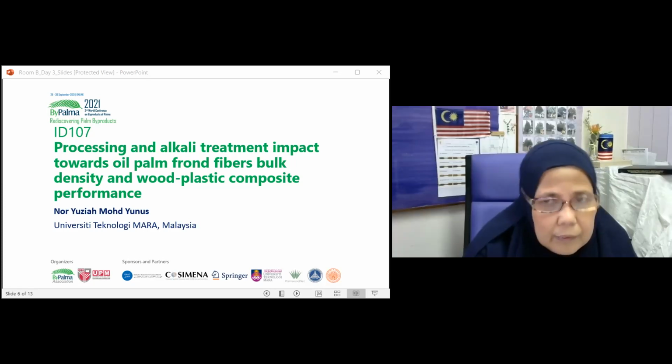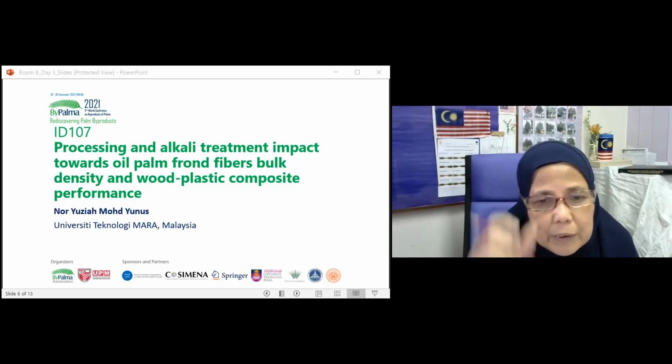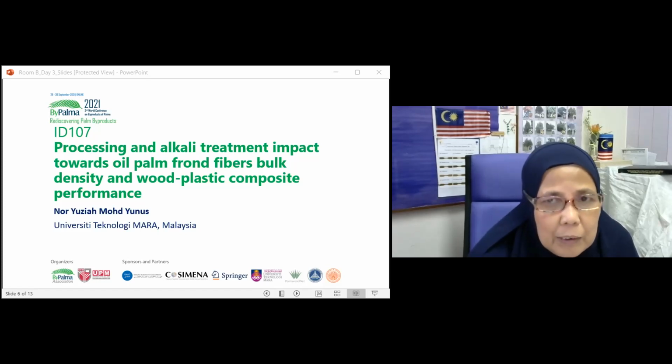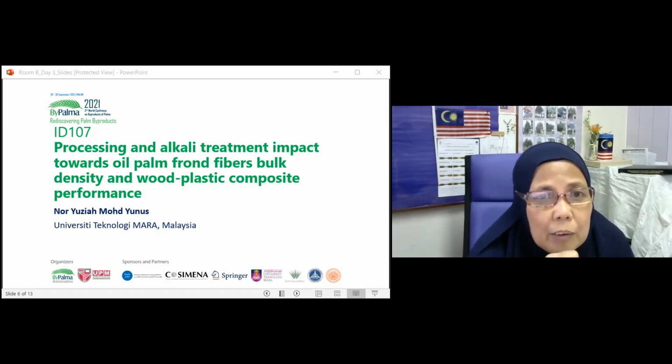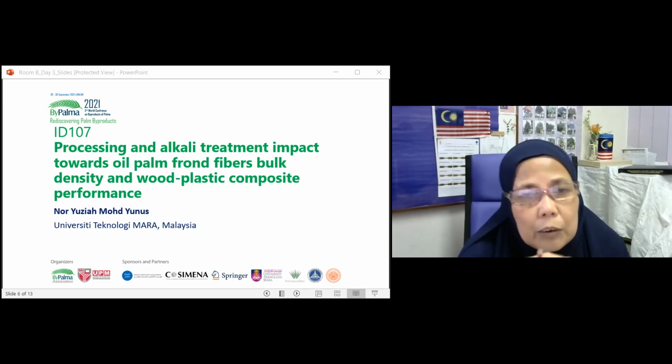Okay, just a quick one. For the impact testing, we did a pendulum test. It's just a simple test, it's not even notched. It's just a simple cut sample and then a pendulum test, because you can actually have both notched and unnotched, but that's it.